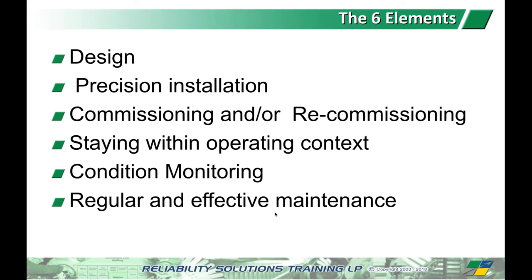Precision installation, how we install it, set the machine up, adjust it, and everything is very important. How we commission or recommission after large overhauls and maintenance is absolutely essential. We introduce an awful lot of failures during that process if we're not careful.